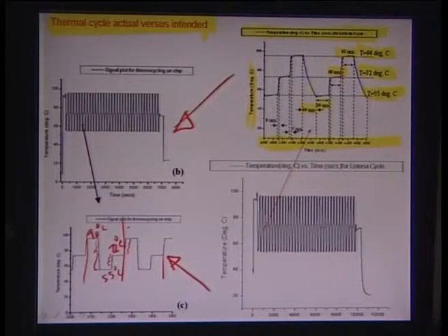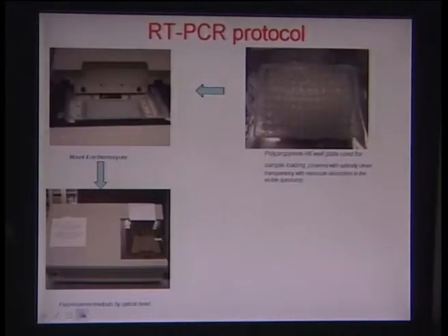As you can see here, the hold steps really are constant, they are not varying much, but what we do vary is the ramp up, ramp down rate immensely, tremendously. And so essentially this is almost reduced from 5 hours to about an hour or so, and better thermal management can be possible with novel means or intuitive designing. One of them I mentioned a few minutes back. Okay, so that's about the thermal cycle.